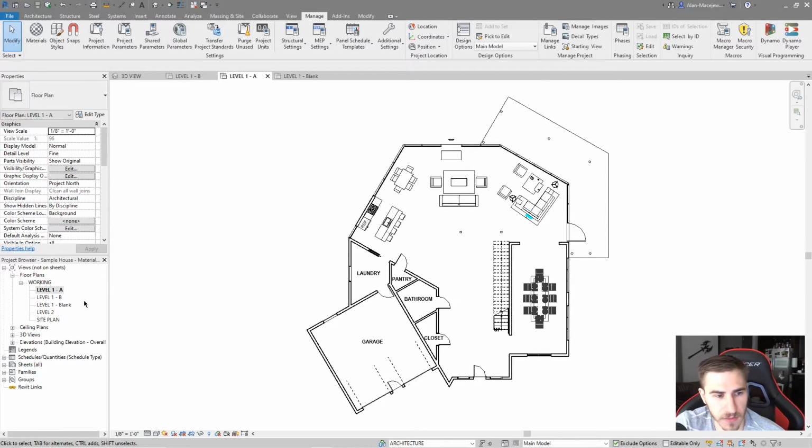But there's a reason I would not delete a particular view. And that's because maybe I've gone to the trouble of setting up a view for a presentation, and I've got A as the primary forever, and it's all set up. That's great. But then all of a sudden B changes to the primary, and I accept it, and that's great. And well, if I delete this first view that is associated to A that's ready for a presentation regardless of the design option that we ultimately go with, then I don't want to just get rid of that view.